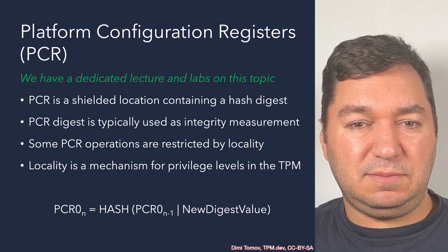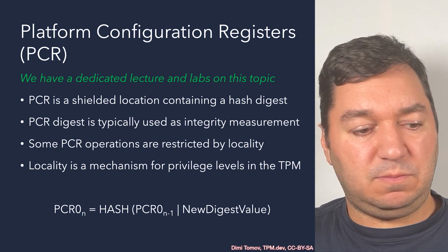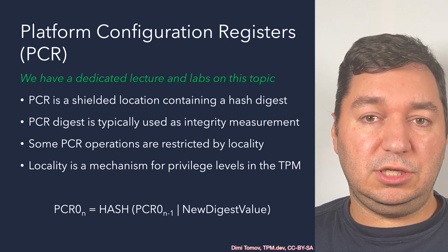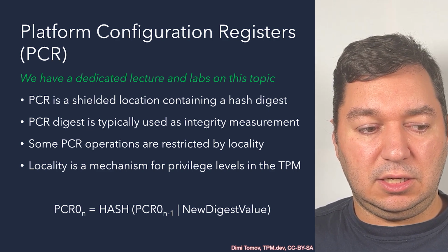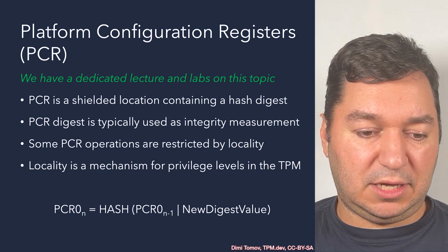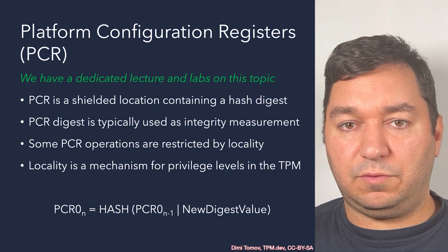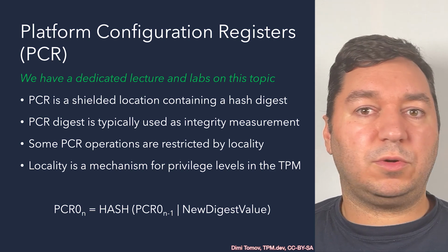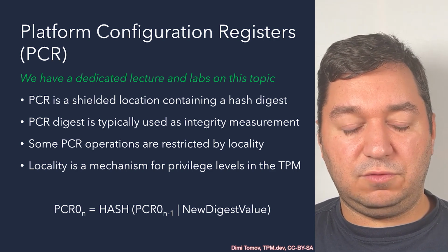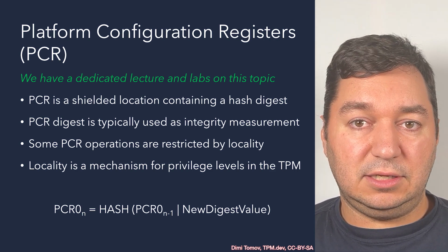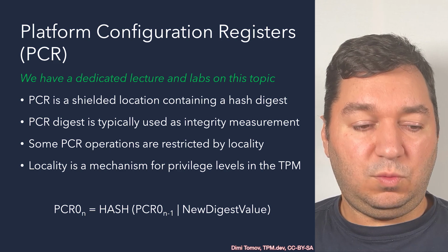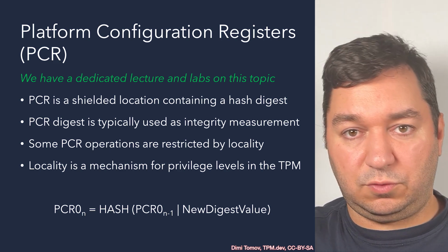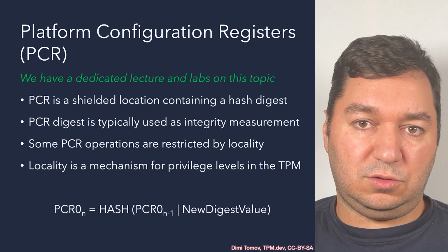And this makes the PCR special. This means that the information that we extend, that we put into the PCR, cannot be tampered with because the system has to be restarted physically, power on and off, which is great. Okay, so then another property of the PCR is that we preserve the old value and we concatenate the new hash digest, which results in another value, another digest that has resulted from the old state and the new state that we introduced.